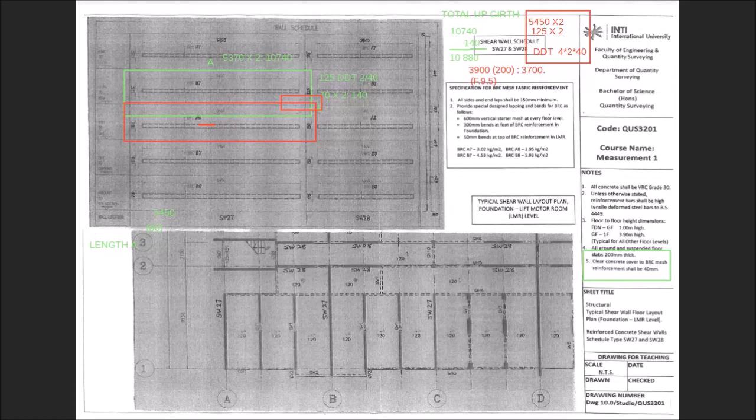Okay, so basically, the trigger line to get the measurement for the item in RC shear wall have been discussed. So what you need to do is discuss with your group member how to distribute the task, and after that, you compile everything and put in the proper way. How many items for the concrete work you have to highlight in the layout plan. How many items for the formwork you have to highlight as well. How many items to be measured for the BRC, you have to refer to the specification here. Okay, different category or different type, different item, and then at the end, when you measure in meter square, you have to convert. Don't forget to convert at the end.